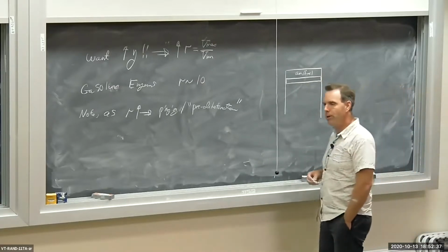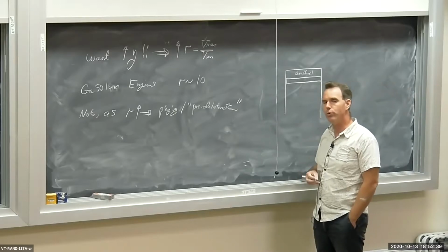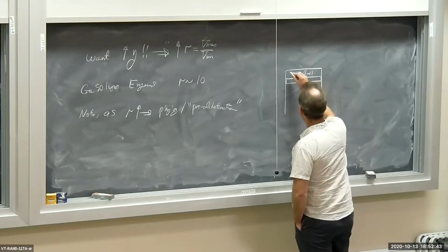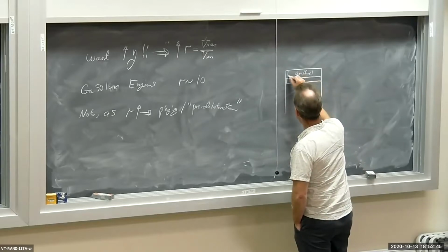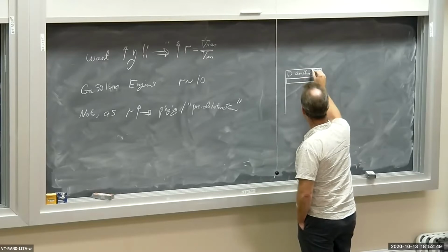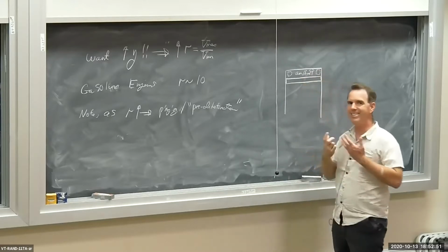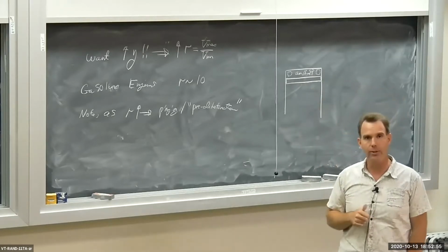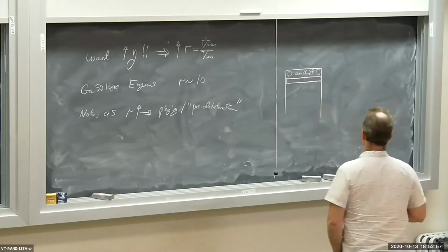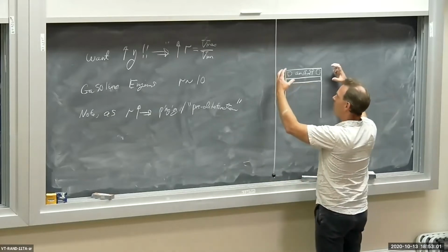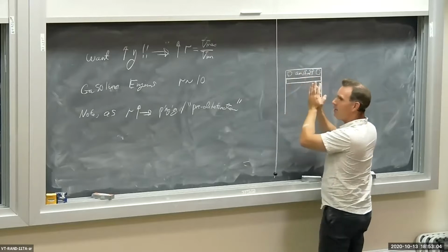If the air-fuel mixture starts to burn or release heat or explode, if you like, in multiple places, so you've got a flame here, you've got a flame there, you've got flames just spontaneously starting to burn before the spark plug ignites the fuel. Pre-detonation.